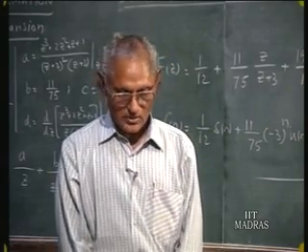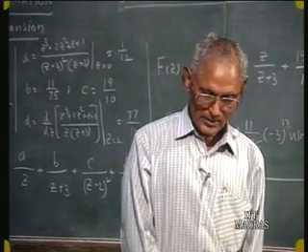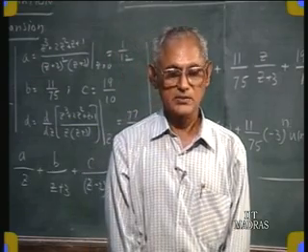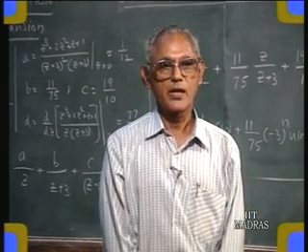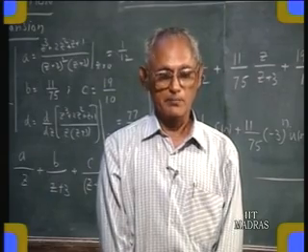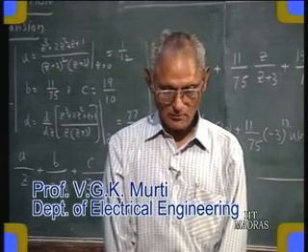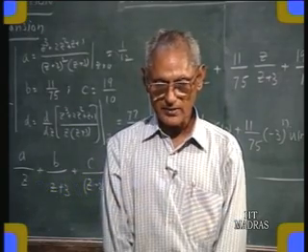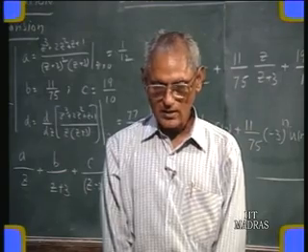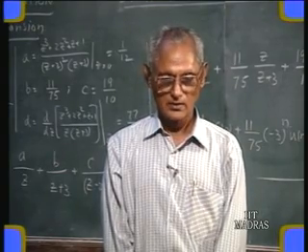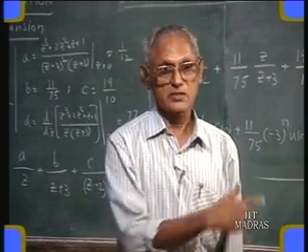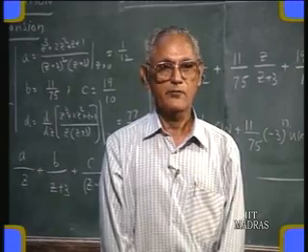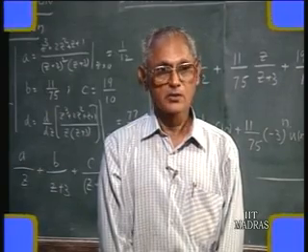And when quadratic terms are involved, we may do it by taking the partial fraction expansion corresponding to two complex poles, or alternately you can associate this with the z transform of a damped sinusoidal function, e to the power of minus n alpha times sin n omega or cos n omega, as the case may be. It is also sometimes convenient, when we have got a complicated term, to view this as the product of two functions and then use the convolution principle to find the associated discrete time function, as the last example showed. We will in the next lecture discuss some of the applications of the Z transform theory and find the solution for the difference equations using the Z transform approach.